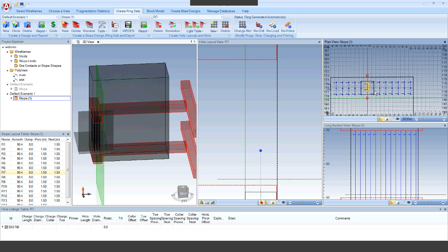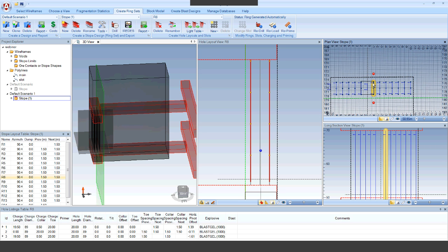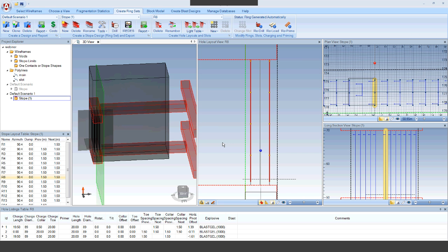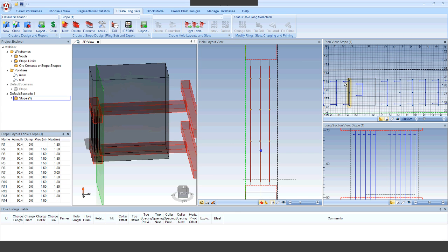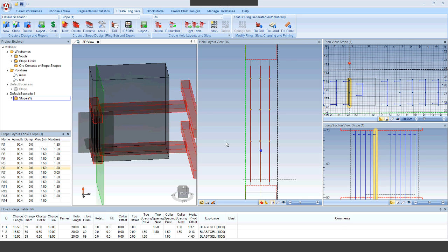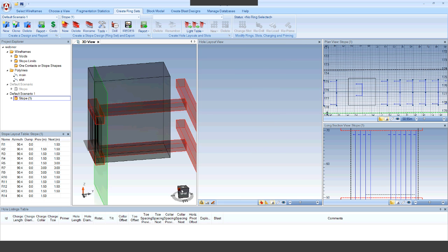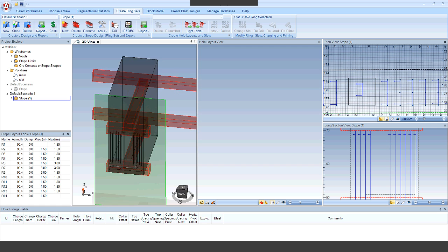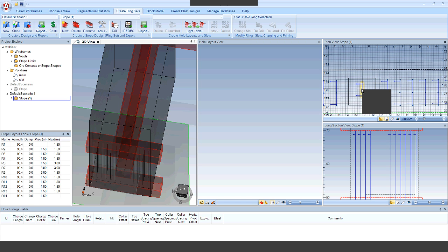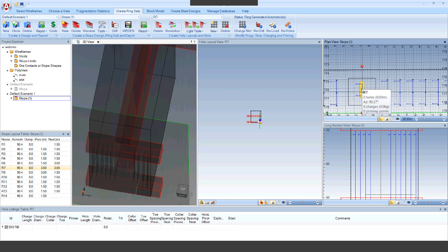The only thing that I'll really need to do is perhaps delete 2 of the rings that are on the far side of this slot. So just by deleting those 2 rings, and if I go through my view on the left side, you see where my slot will be contained. It will be within this main area in there.